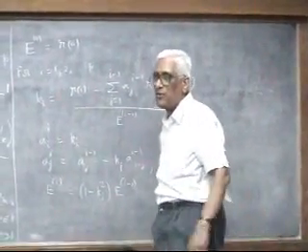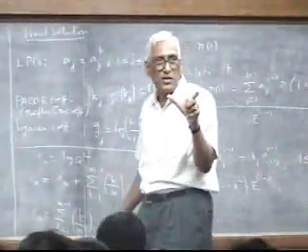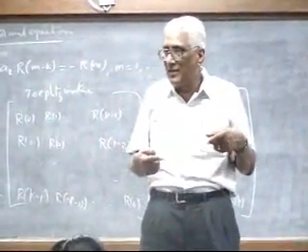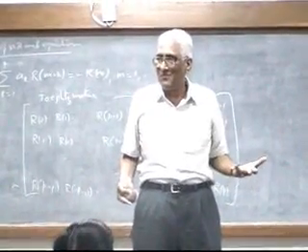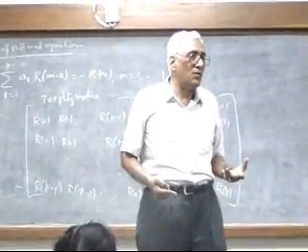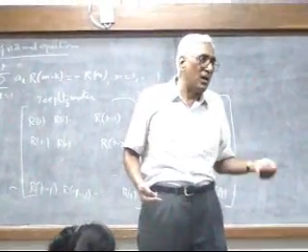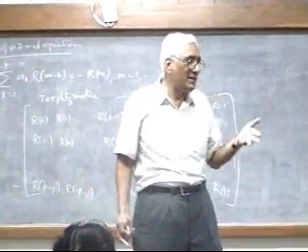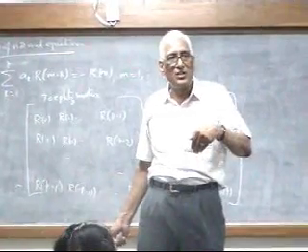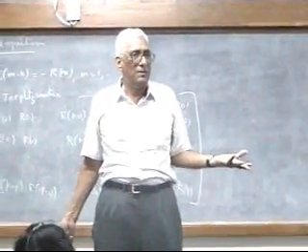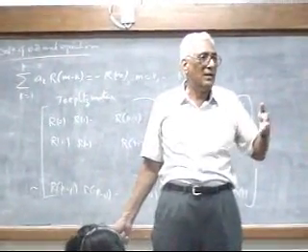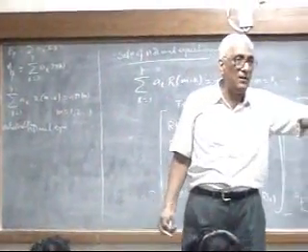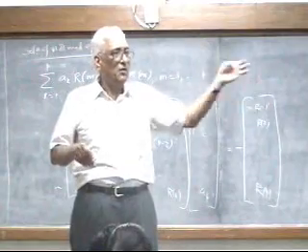It is also obvious now, coming to think of it: given some data, you are doing a linear prediction on that, and if you increase the order of prediction, what do you expect? The error has to come down. If the error does not come down, then the extra piece that you allowed will have to be 0. That means those coefficients have to be 0. That means you are not able to reduce any further by looking at more of the past samples. You looked at past p samples. Now if you want to look at some more samples, the error is not coming down. That means why do you want to look at them?